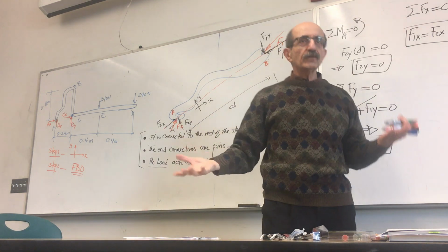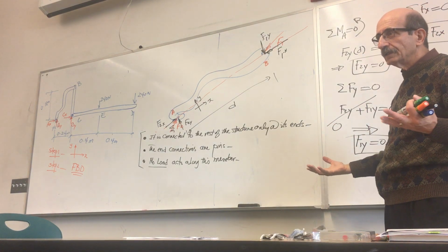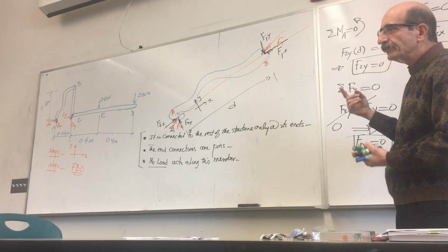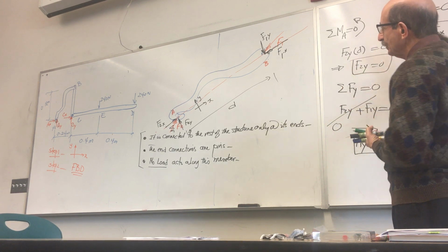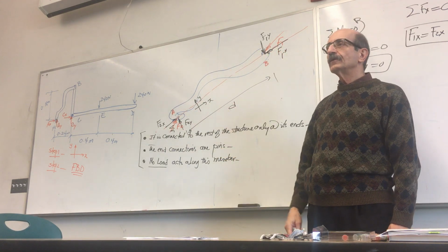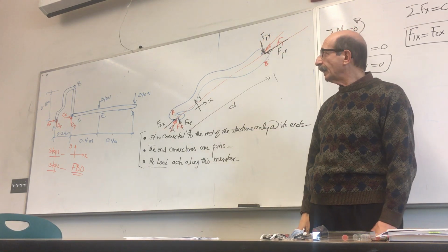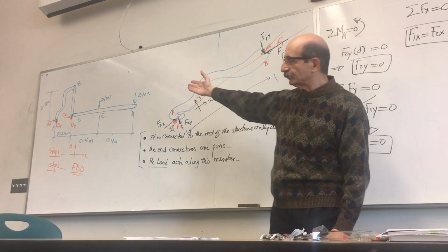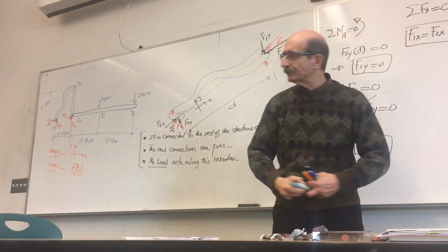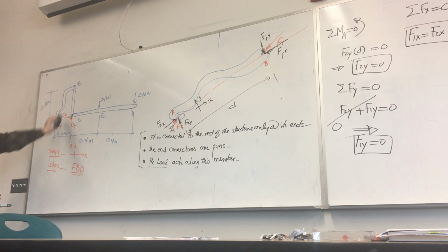So regardless of the shape of that piece, no matter how it looks, you always have forces that act at the two ends, acting along a straight line connecting the two, and these two forces are equal. So this member represents one unknown force and not two. So going back to that example, what that means is you have a member, you see this member now?